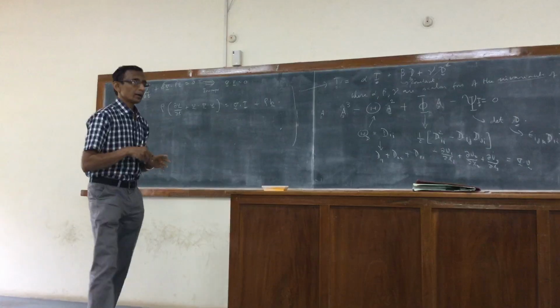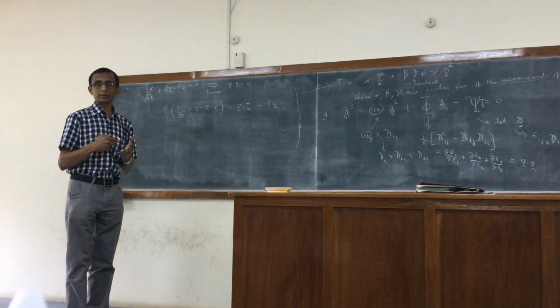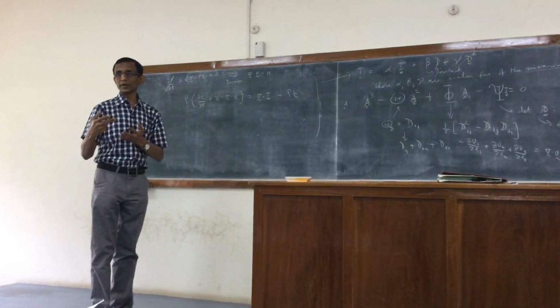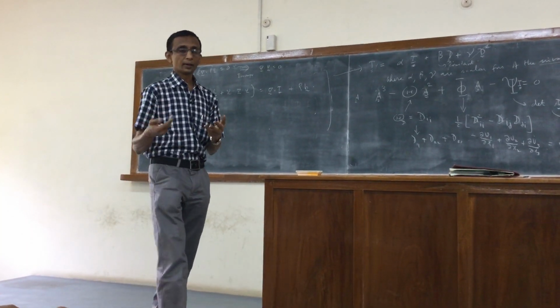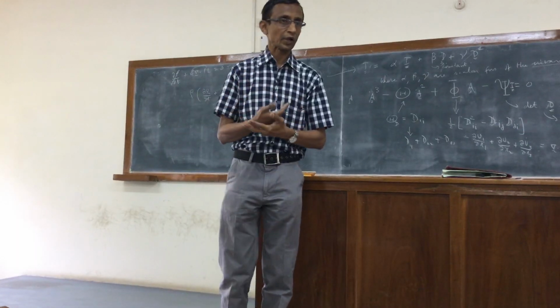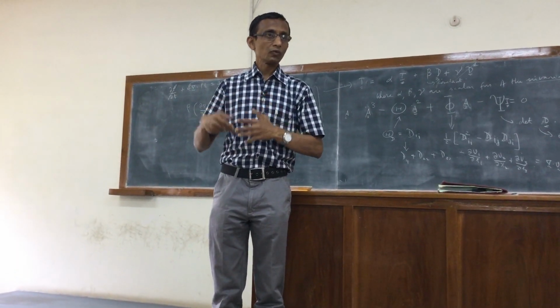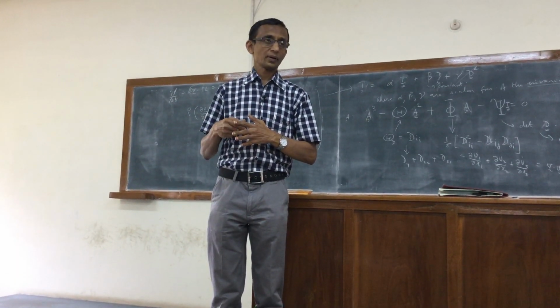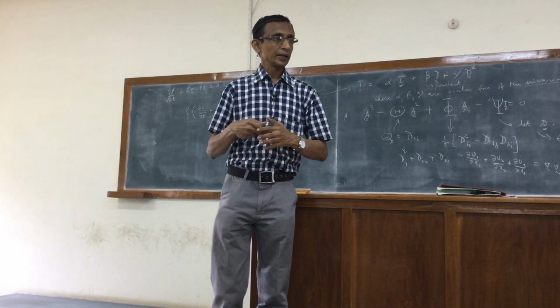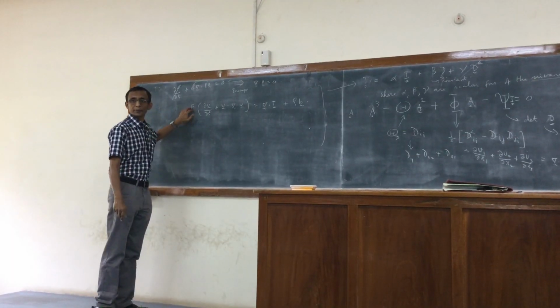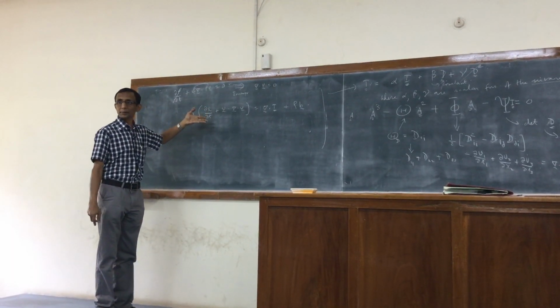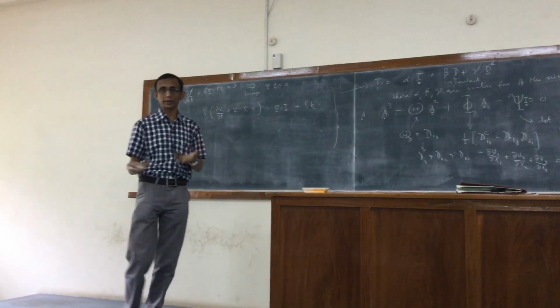So, earlier we said I have 4 equations for the 4 fields. One is the density field, which is a scalar field. Another is the 3 components of the velocity. So there are 4 variables, 4 equations. Right? So now the density is a constant, it has to be specified. It becomes a parameter. You have to specify what that constant density is.